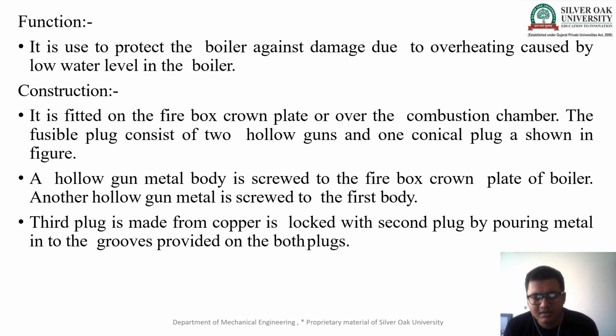Sometimes, if the weight is jammed, at the topmost position we have a black valve made of gun metal. If the temperature is higher and the weight does not lift, the valve will melt out. Once the valve is melted, we can find a hole, and from that hole the steam gets out of the pressure cooker to the atmosphere.